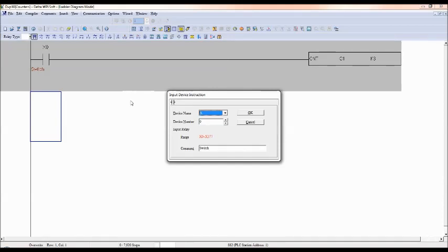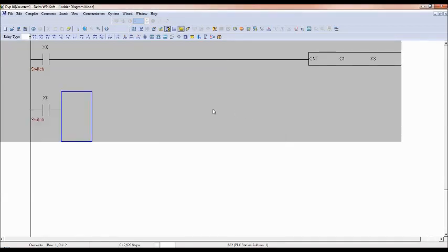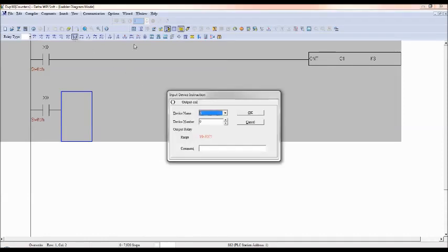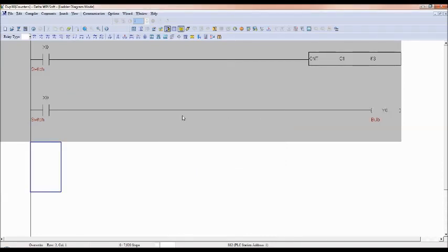So I'm going to switch on the contact. X0 is the switch on contact. Then I'll take the output, which can be an LED or a bulb; for my example, a bulb. The bulb should be on after pressing the switch 3 times. Very simple. There is one more concept: in counters you have to use reset. I'll take that up next, after explaining this one.